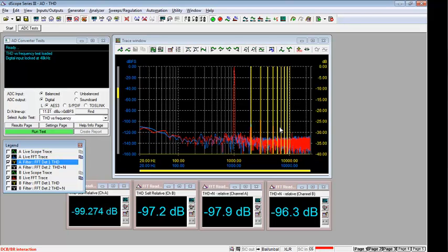And you can't do this with a conventional notch filter. You have to use digital frequency domain analysis and use these ideal brick wall notch filters in order to isolate just the harmonic distortion energy. So I have to use an FFT to get this THD result. Hence I'm sweeping FFT based measurements, which is slower than sweeping continuous time based measurements, but we can do a lot more with these FFT derived results.